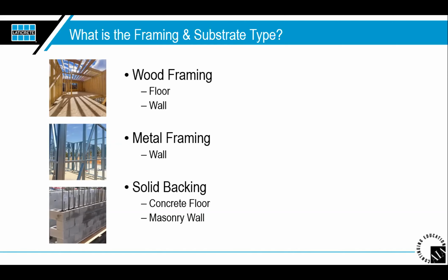Concrete floors must meet deflection and have no curing compounds or sealers present. If the concrete is cracked, an anti-fracture membrane is probably going to be recommended to prevent damage to the tile or stone. So another big thing that we're seeing out in the field is the fact that we want concrete to dry faster, and that is a tough subject for tile, specifically for tile and flooring companies, because we'll have a floor that's been laid maybe for just a couple of days, and hey, can we